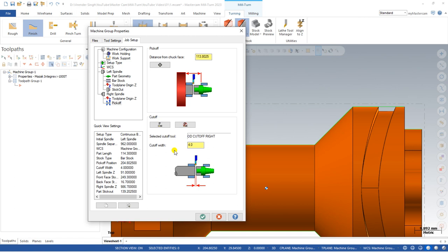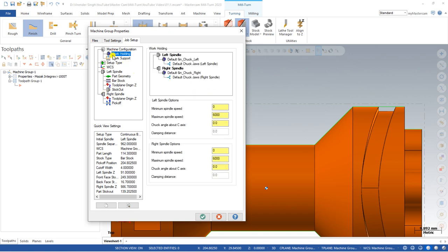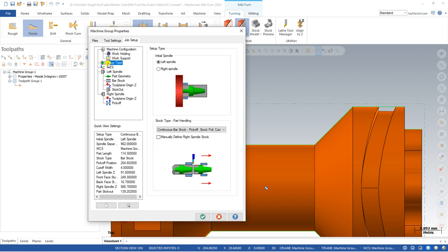If you miss anything from that portion, you will get issues when you are creating the tool path, when you are creating the project, and multiple issues would come. So you have to make sure you check all these points in a proper way. First, you have to define the stock setup properly, according to the machine and the working area, and define the workpiece type properly.